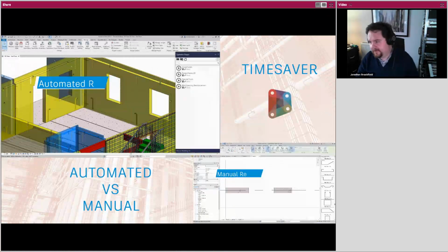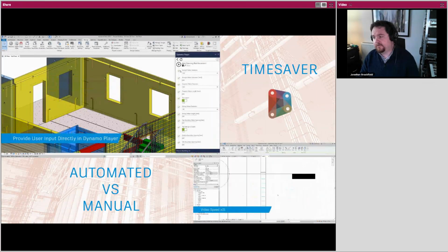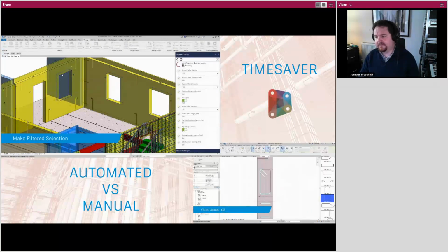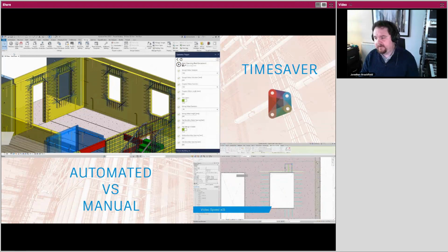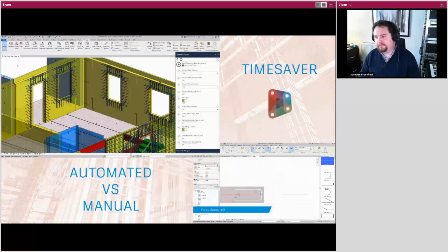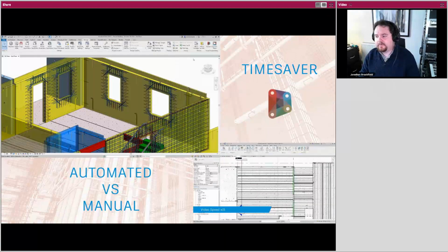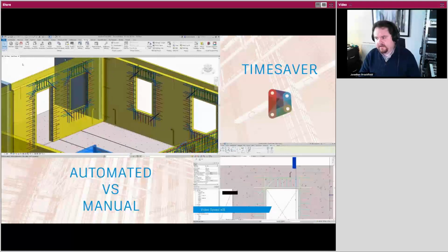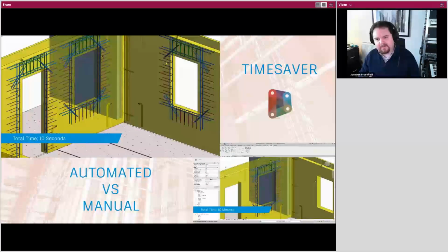Now let's look at two short videos running in tandem. The one in the lower right-hand corner shows the manual process of creating reinforcement bars surrounding a window opening. This video is 15 times its original speed. The second demo shows the generation of rebars for several window openings and doors, simultaneously using a Dynamo script that is run via the Dynamo player. The difference between the traditional manual modelling and the automated one is abundantly clear, and the value added by automation is gigantic. In this example, the user was able to speed up the concrete detailing process about 60 times.